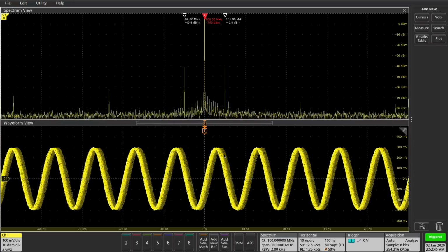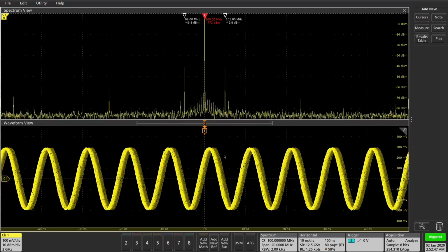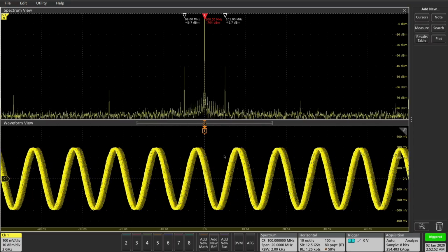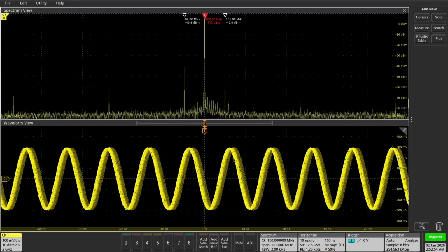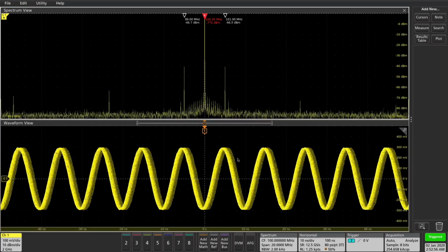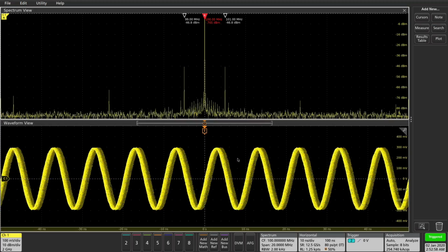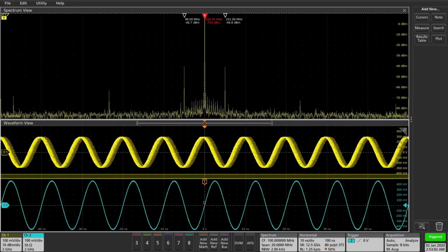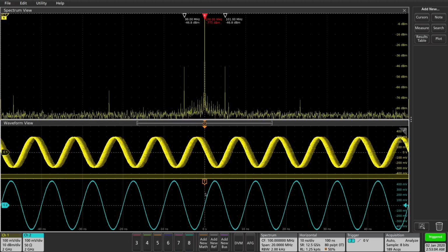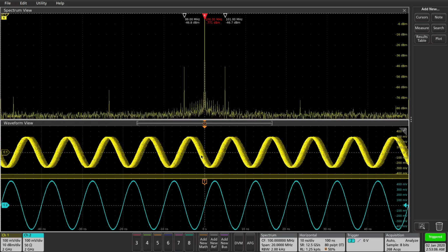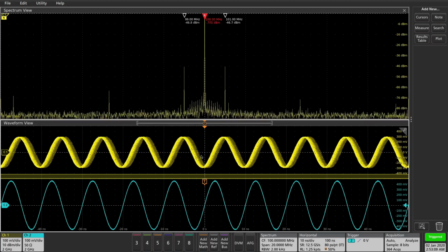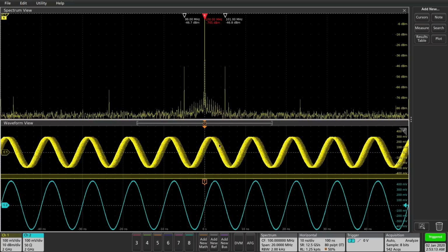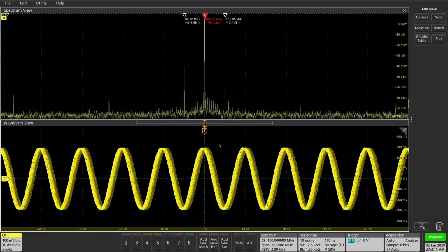This is most likely a bug in the firmware that I would have to report to tech so they can fix it. So the signal is moving back and forth at 10 kilohertz, but there is now a fixed offset, and that's why it drifts with respect to the other channel. If I go ahead and enable the other channel so you can just see what the other channel looks like, here's the other channel. So we're triggering on this one, and even though they're both supposed to be centered at 100 megahertz, there's going to be some shift. So it doesn't go up and down by the same amount with FM modulation. So this is all really interesting and basically confirms everything we were talking about.